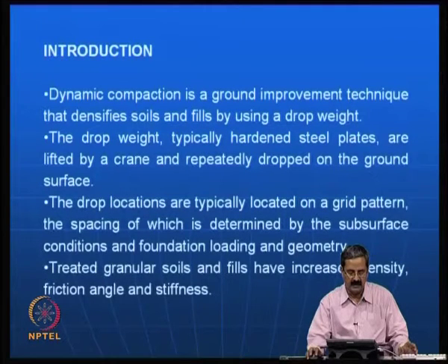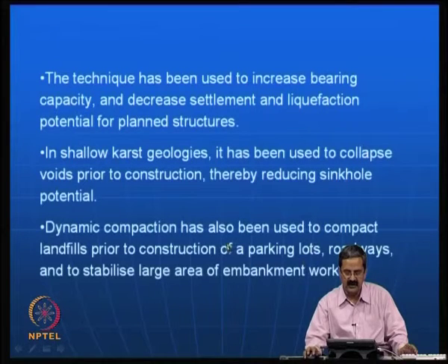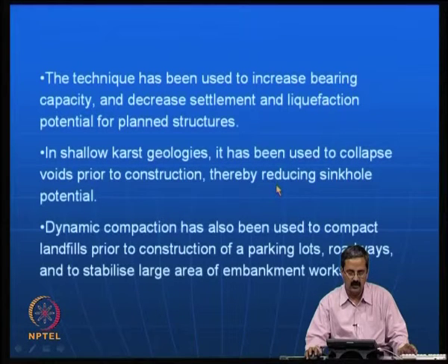Normally, treating granular soils and fills has always resulted in increased density, friction angles and stiffness. We will see how this can happen. As I just mentioned, this technique has been used to increase bearing capacity and decrease settlements and liquefaction potential for plant structures. In fact, this is one of the very important applications, and in shallow karst geologies where the soil has a tendency to collapse, it reduces the voids prior to construction, so that the potential for sinkhole formation is reduced.